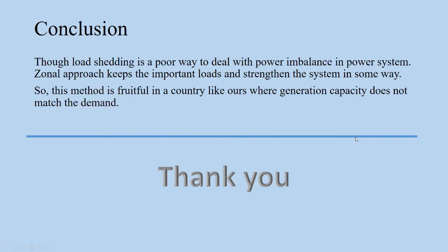Finally, load shedding is not desirable at all to deal with power imbalances in the power system and should be used as a last resort. Using a zonal approach in load shedding helps us obtain better nadir frequencies and rates of change of frequency so that we can restore the frequency to its nominal value faster. This method is very useful for our country where generation capacity cannot meet the demand of the users.